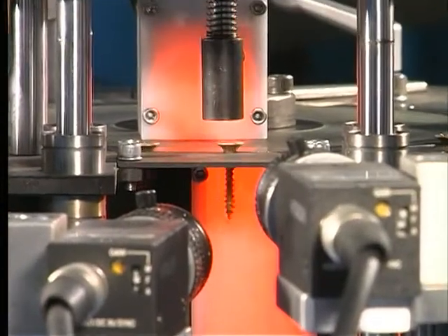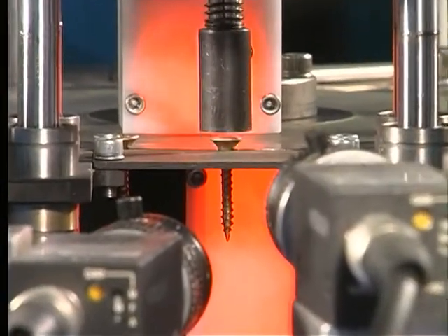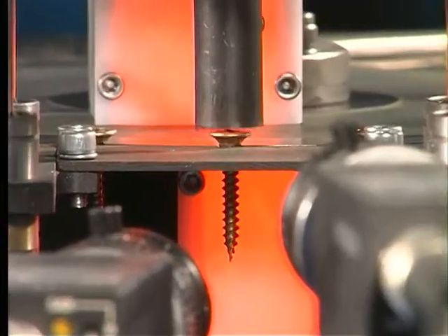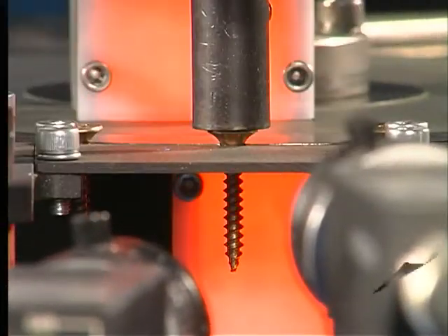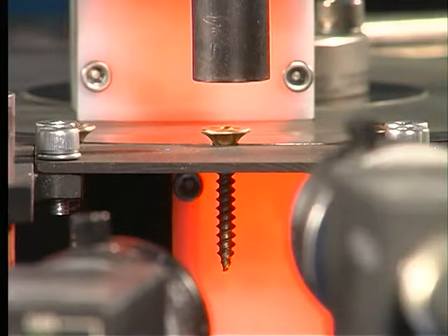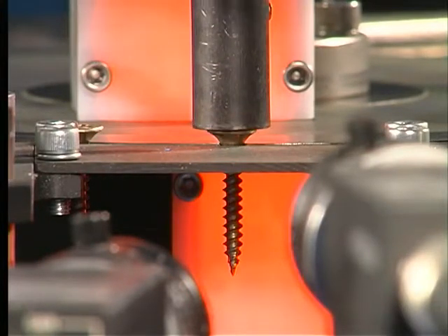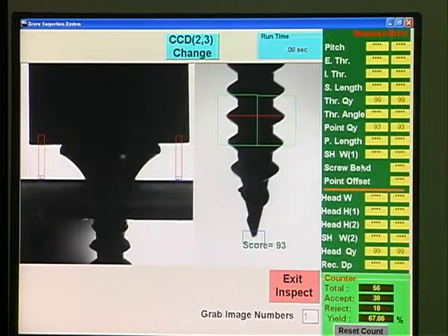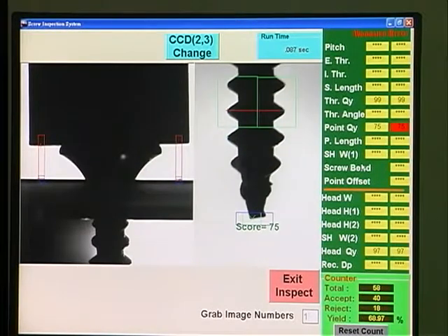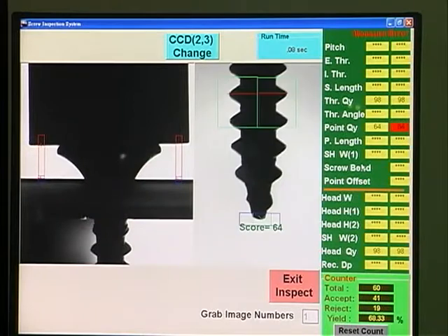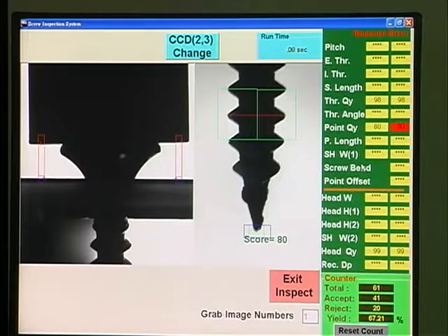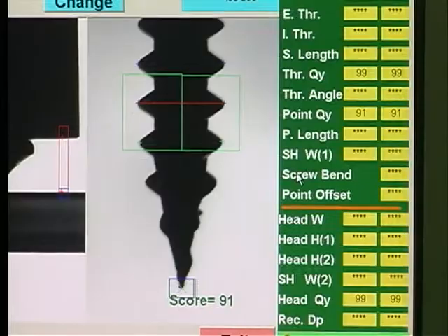The cone points are inspected by comparing the incoming screws with a sample previously taught to the program. The passing level is determined by a required level of similarity. The evaluation of similarity is based on the theory of pattern matching, without further assistance from the camera.